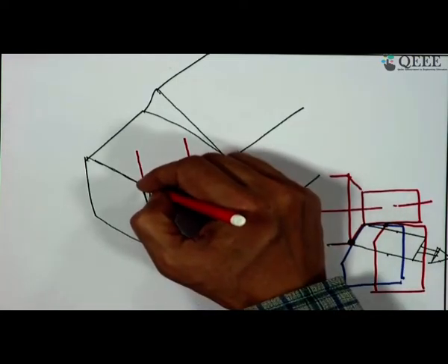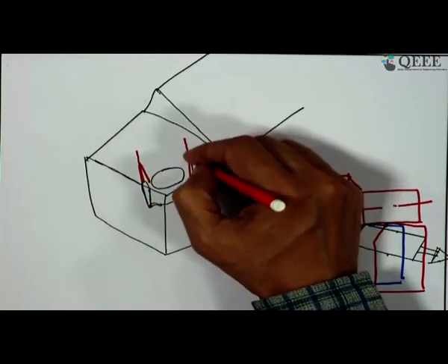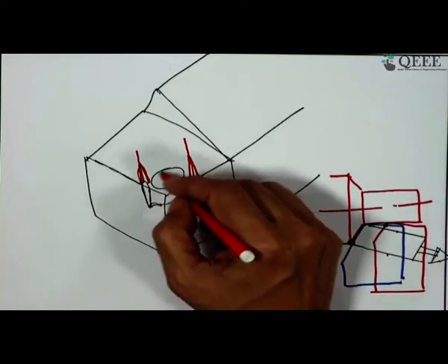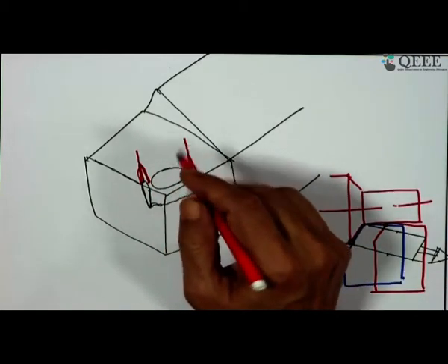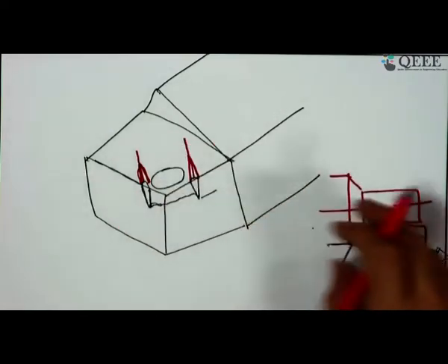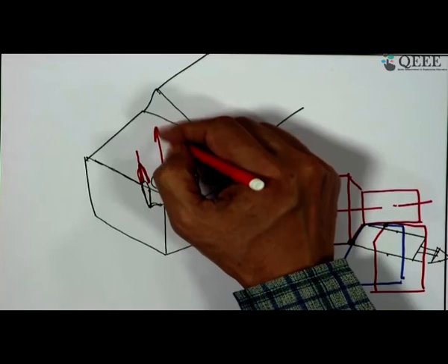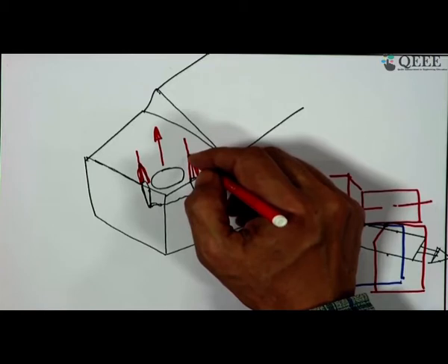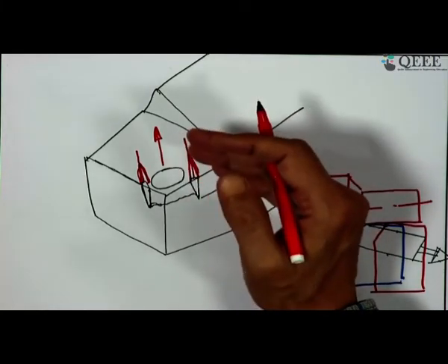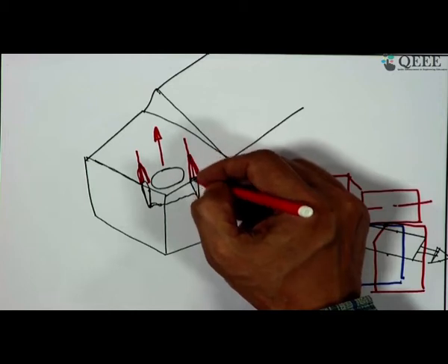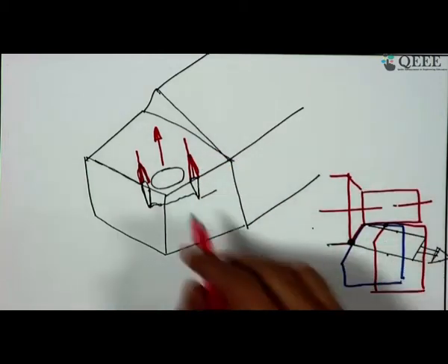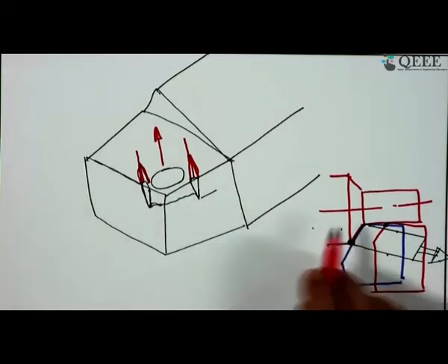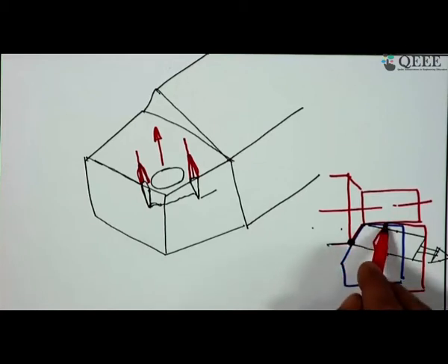So, along this you can also have this sliding mark, and these are called sliding wear. So, friend, please note down, on the rake surface you have the crater formation, plus along the two edges of the chip in the direction of chip flow you have the sliding mark, and it will end here because of the lifting of the chip, it gets separated, and if you continue down the flank you get the location of the notch. So, this side it is the rubbing action of the workpiece, and there you have the notch formation because